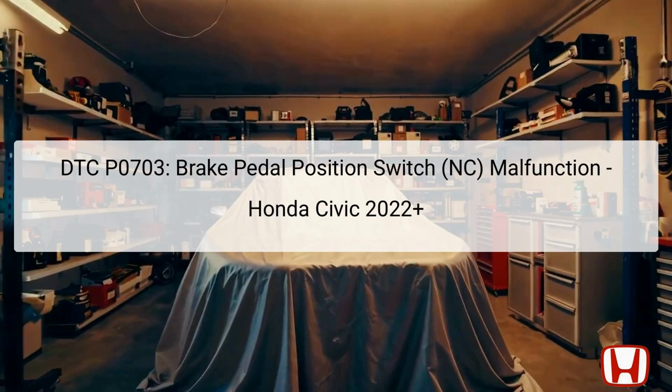The brake pedal position switch is located near the brake pedal assembly, typically mounted on the bracket where the brake pedal connects. When the brake pedal is pressed or released, the switch status changes, which the PCM monitors for proper functioning. If there are inconsistencies between brake pedal operation and the switch's signal, the PCM will store this DTC as an indication of failure, alerting the driver that maintenance is necessary to address the issue.